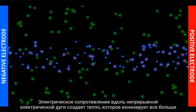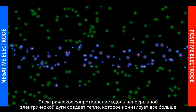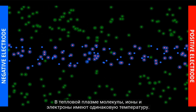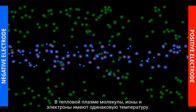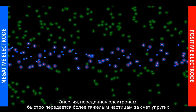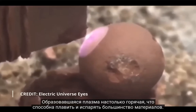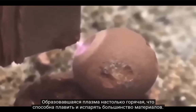Electrical resistance along the continuous electric arc creates heat, which ionizes more gas molecules, gradually turning it into a thermal plasma. In a thermal plasma, the molecules, ions and electrons are all at the same temperature. The energy given to the electrons is dispersed rapidly to the heavier particles by elastic collisions. The resulting plasma is so hot it is capable of melting and vaporizing most materials.